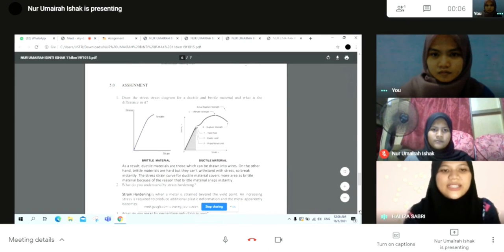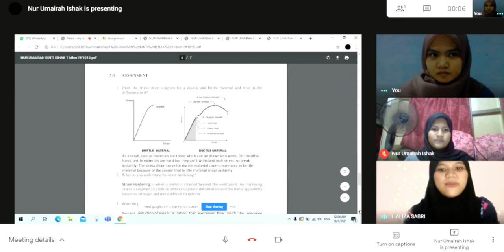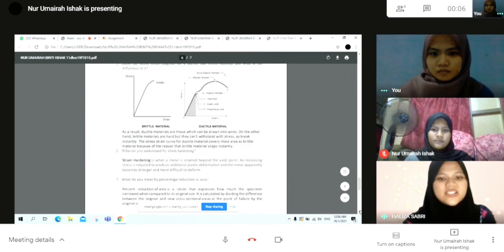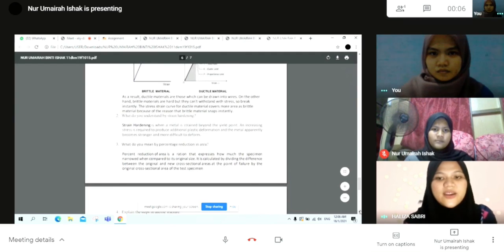On the other hand, brittle materials are hard but they cannot withstand stress, so they break instantly. The stress strain curve for ductile material covers more area than brittle material because brittle material snaps instantly. What do you understand by strain hardening?